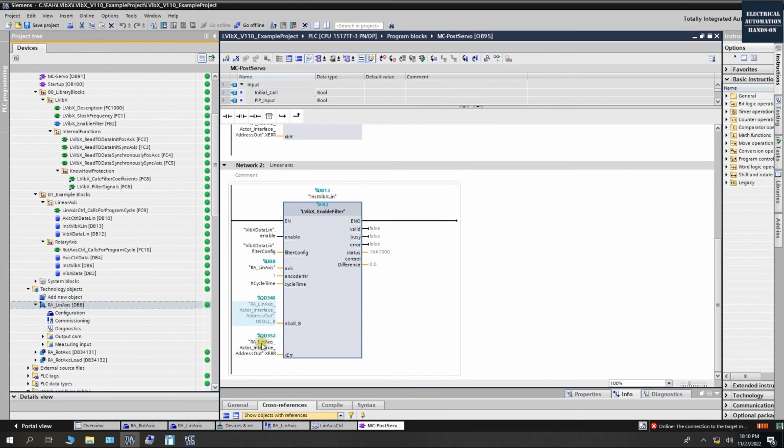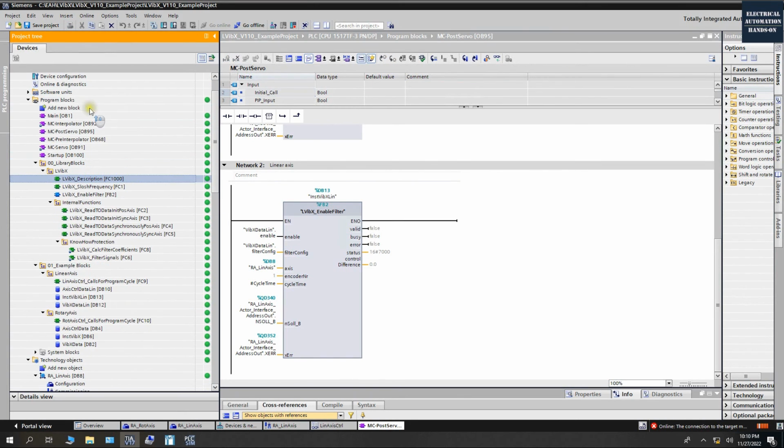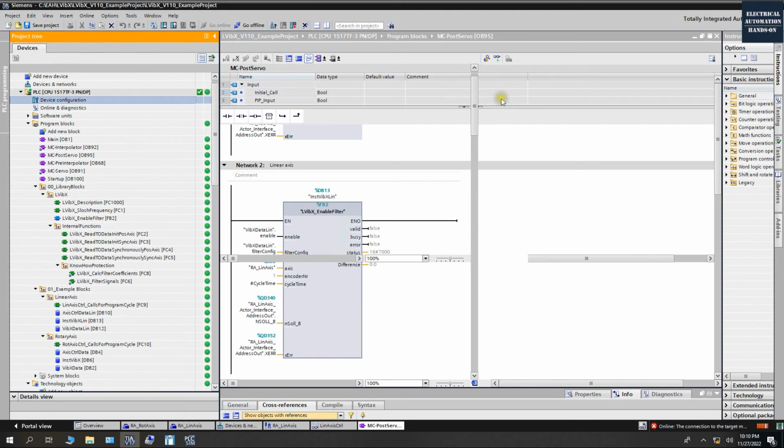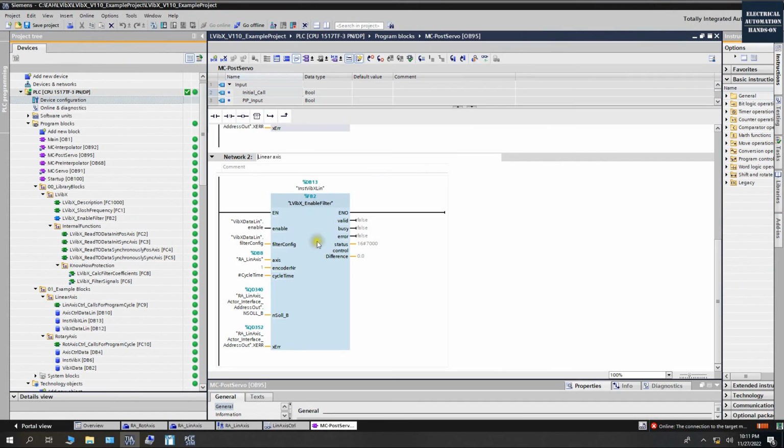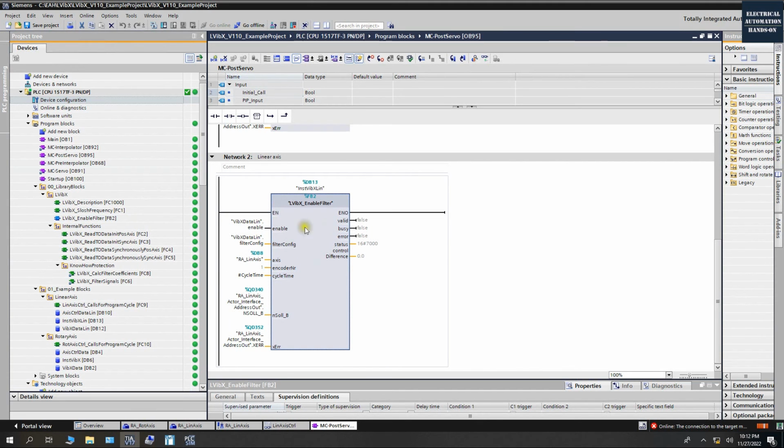In the meantime, we connect to this output here, 340 and 352. This is the axis output. Those hardware addresses we can find by going back to the hardware configuration at the drive side. If we go to the drive side, we can see the outputs are here. So you need to connect this QD address to the function block. So this function block joins this oscillation feature with this axis TO. This example includes everything, so it saves us time and you can digest more details.